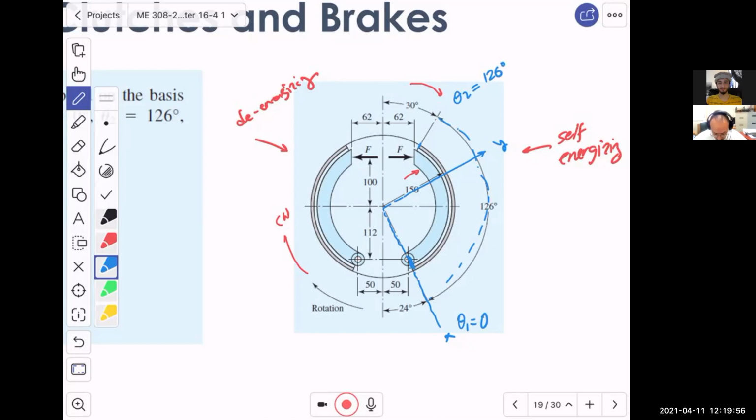Yeah. All right. Now, the next thing, what is C? What is C? C is the distance from the pivot all the way to the line of force, this actuation. So how much is it? How much? Anybody? 212. It is 100 plus 112. All of this.